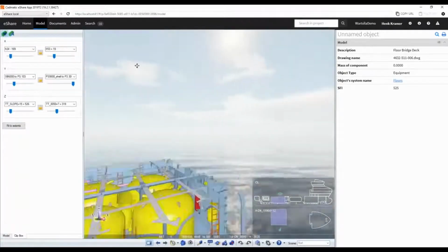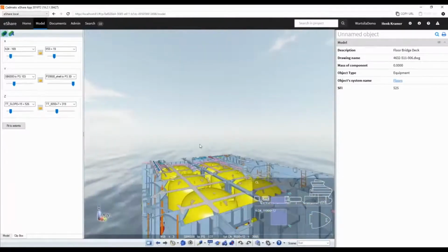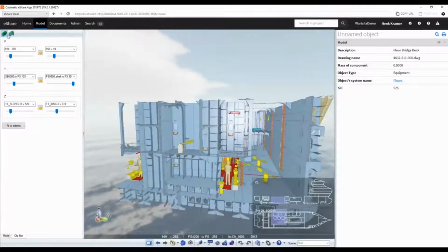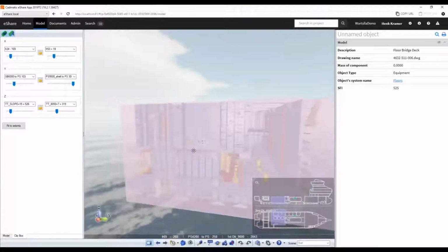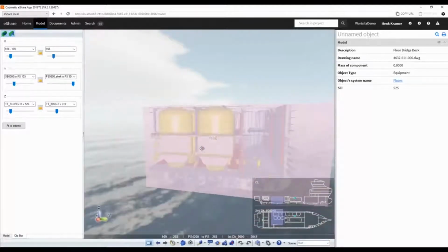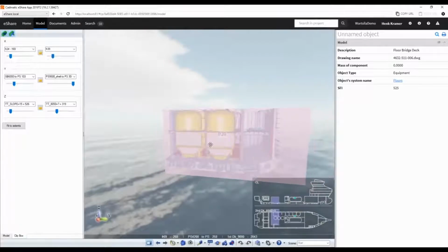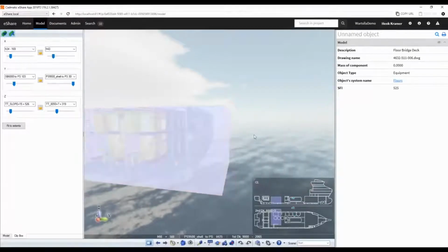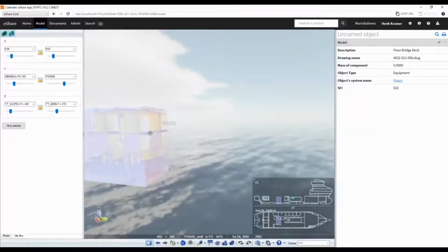And by having clipped the vessel, it is much easier to see what you are currently working on. This also works in the view by just a right mouse button. You can easily shift. Again, you have the coordinates of the frames that you are working on. And from the side, again, the coordinates, so you immediately see what you are clipping on. It snaps to the nearest main point, but you can also manually type it with what you have in mind.